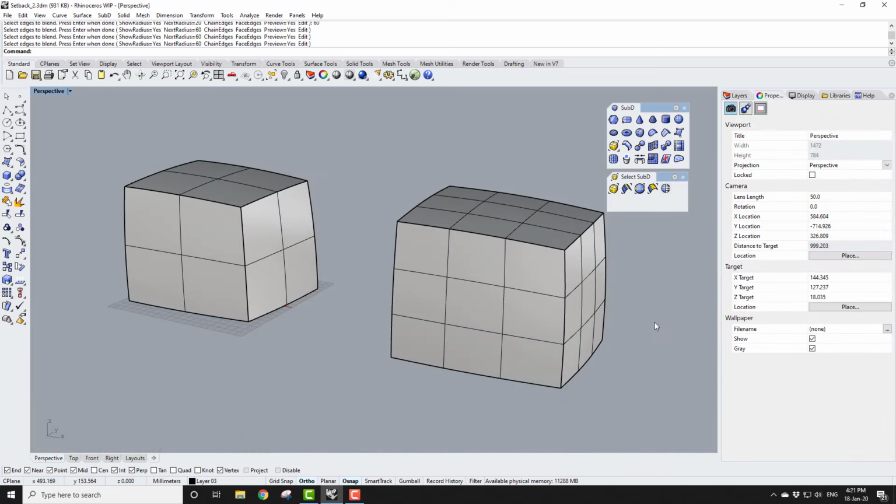Earlier in the video I looked at building a sharp-edged polysurface equivalent as a single SubD object with creased edges. Very often in NURBS modeling, starting with controlled sharp edges is the correct way of creating fillets, blends or transitional surfaces. And very often this geometry is better suited to a NURBS workflow.